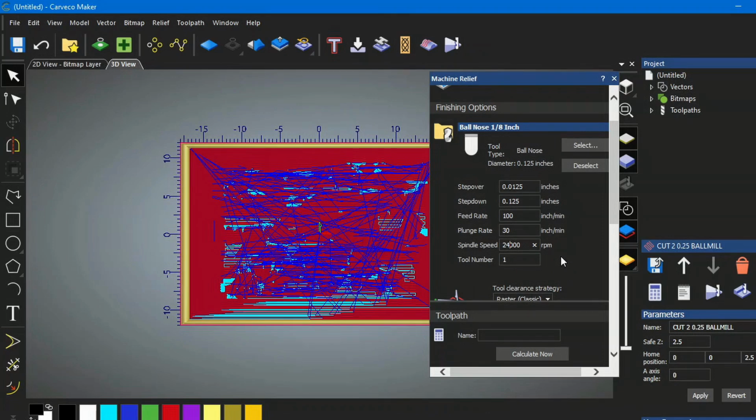Bearing in mind that whether using Mach 4, Mach 3 or an SMC5 external controller, you can run this code at, you know, if you wanted to, 200 or 300% of these values apart from the RPM, and that is how you can change on the fly, as it were, of cutting.